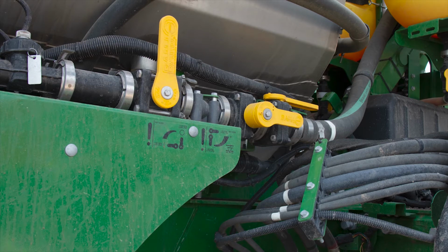Basically, a standard flow system flows at about 170 gallons per minute on the top end. So if we're looking at doing high rates of liquid nitrogen or liquid fertilizer for that matter, we can put out about 170 gallons a minute with our standard flow. The R4038, the R4045, and the R4060 can all be equipped with a high flow system, and it's often referred to as a dual flow meter system as well. Those systems increase capacity by about 50 gallons a minute. 225 gallons a minute is our max flow on our high flow systems.